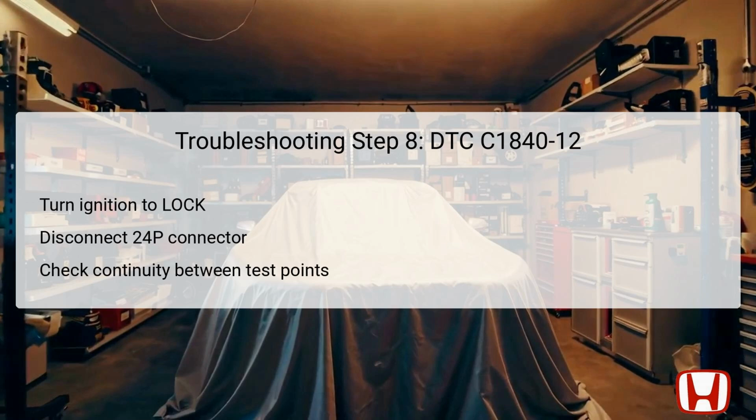Confirming continuity between these wires suggests that the connectivity is intact, allowing you to consider updating the software of the real-time AWD control unit or replacing it to restore optimal function. If the continuity test fails, this indicates an open circuit in the SG wire, and repairs would be necessary to restore the connection between the sensor and the control unit. Thus, this step is critical in ensuring the entire control circuit operates correctly.